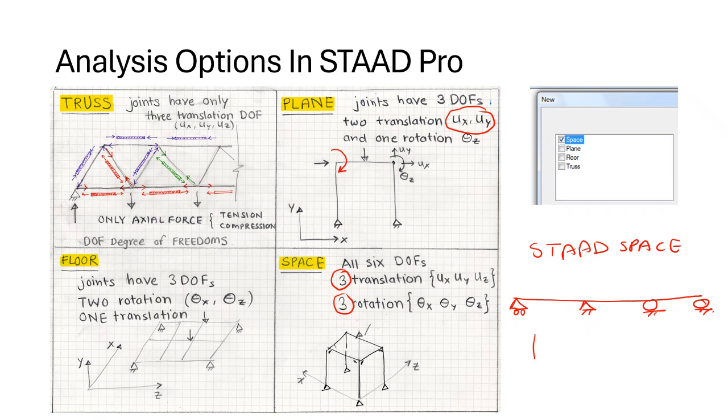When the 2D drafting softwares came into the picture, they had an X, Y plane, and we would put points and lines in the XY plane. So STAAD also started with Y up. The gravity direction in STAAD is minus Y by default.